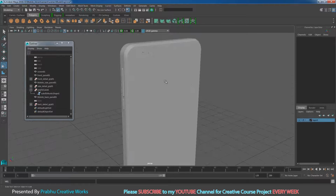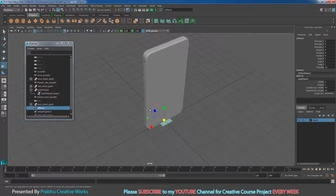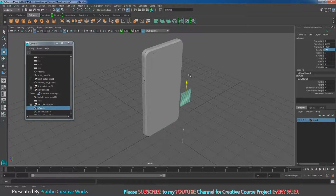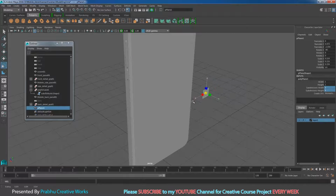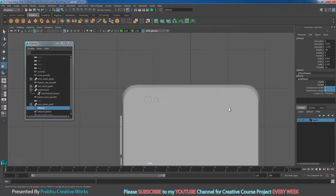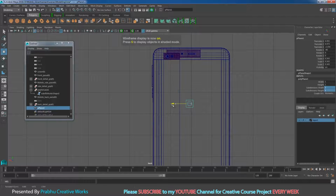So I want some logo over here, so I will click on polyplane. So press E on the keyboard. I want to rotate this one by -90 and press W and move in Z and move in Y. So I want to give subdivision width and height 1. So press R and scale smaller. So go to back view, press 4 on the keyboard. So I want to keep my logo in this area.